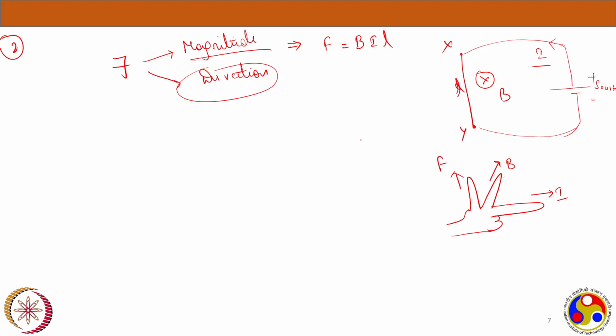Now, in this scenario, can you tell me what are the directions of our notations here? We have a current direction from right to left here. I have taken the middle finger here, and the magnetic field is nothing but the forefinger, into this one.